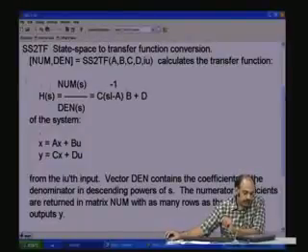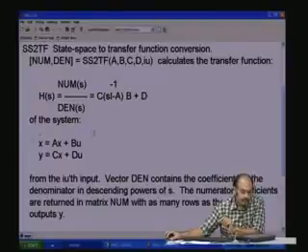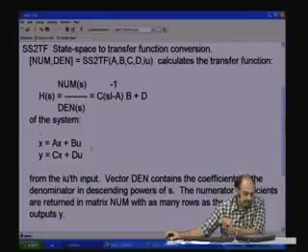And this will basically use this kind of an algorithm, C (sI minus A) inverse B plus D. In fact, this is what we derived in the last class, if you remember, of this particular state space form, where A, B, C, D matrices are as defined for a general state equation. So, let us